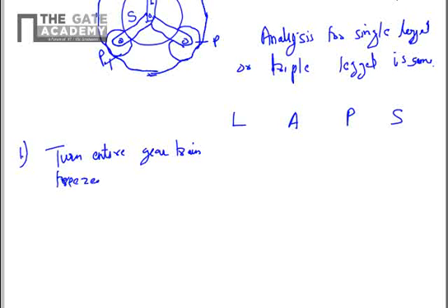So there is no relative motion between the different gears: clockwise plus one revolution, and everything will revolve clockwise plus one, plus one, plus one. All the gears are frozen. There is no relative movement.